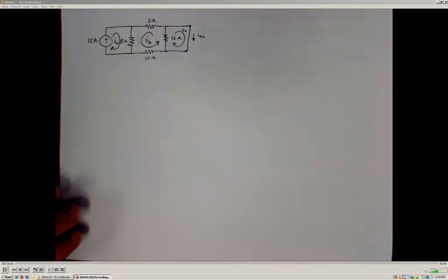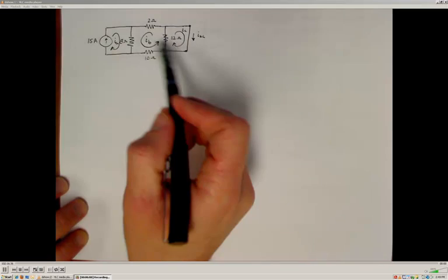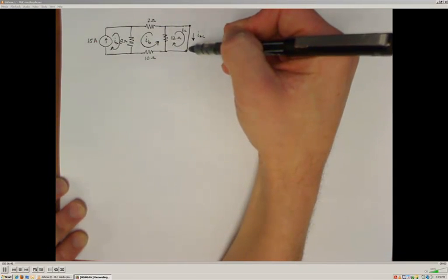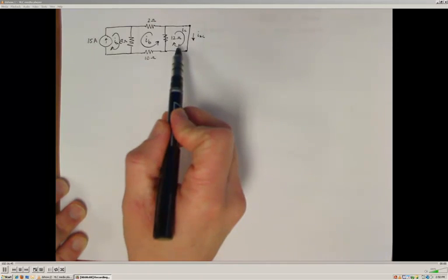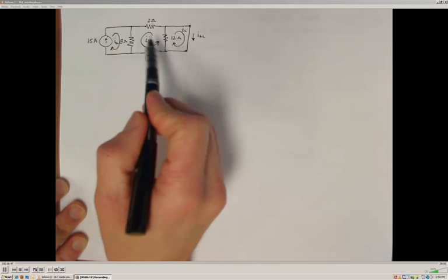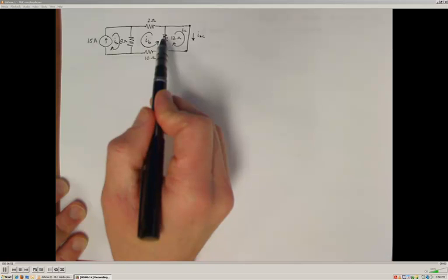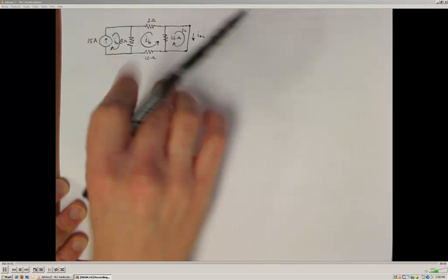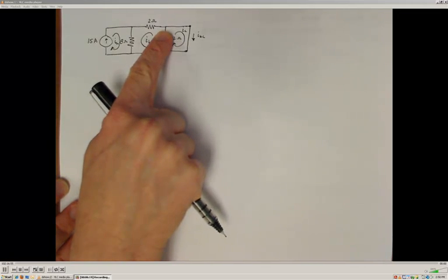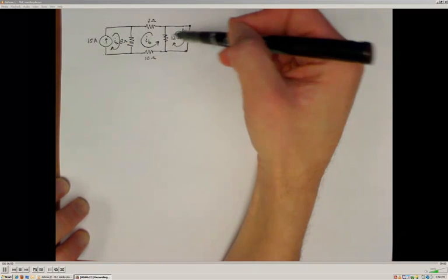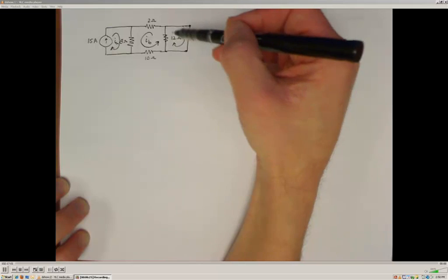Alright. Again, the potentials that are developed are going to be different because these two terminals are connected directly with a short circuit. We also do not have to directly solve for IC. What we could do is just recognize that no current is going to flow through this 12 ohm resistor here, and we could just completely remove it from the circuit and solve for that directly. But I'll just want to show you that even if we don't make that assumption,